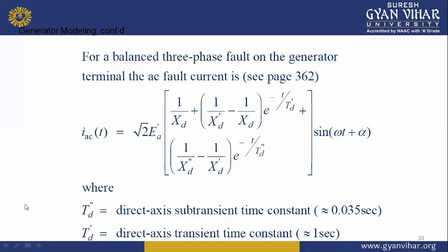The circuit breaker must of course interrupt the current much before the steady state conditions are reached. Immediately upon the short circuit, the DC offset current appears in all the three phases, each with a different magnitude, since the point of the voltage wave at which the short circuit occurs is different for each phase.